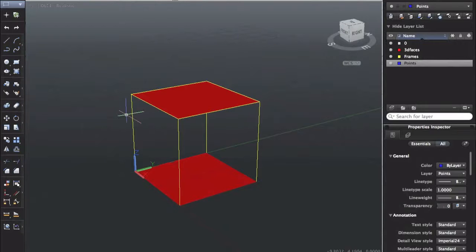One more thing that's very important to remember: you always need to remember your Z direction, where it is. By Z direction, I mean the direction that is up. That direction may be Y or X depending on how you decide to orient your model axes. In this case it is Z, so you just need to remember which way is up and the units that you're using. So let's move on to the small machine that I've got right next to me at the moment and run the simulation on SAP 2000.